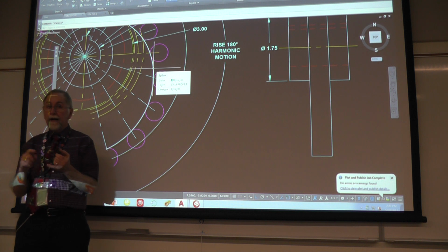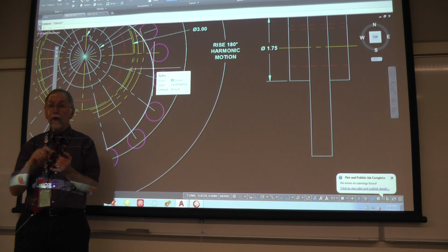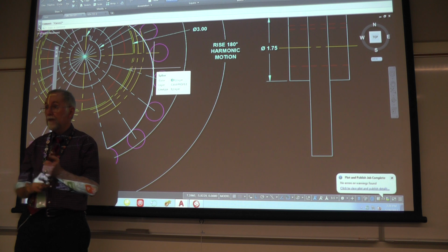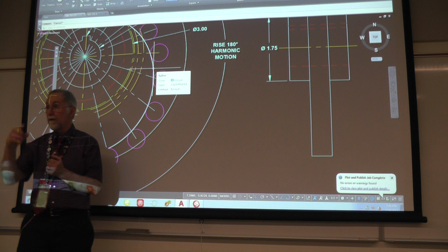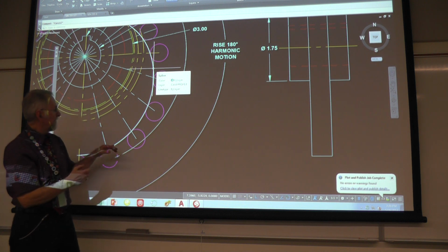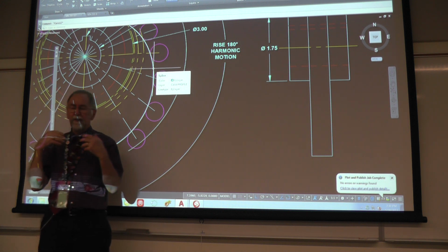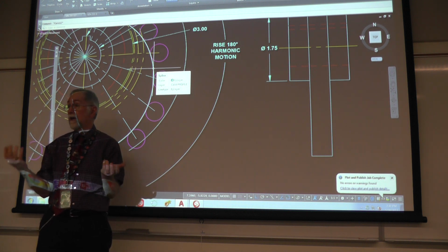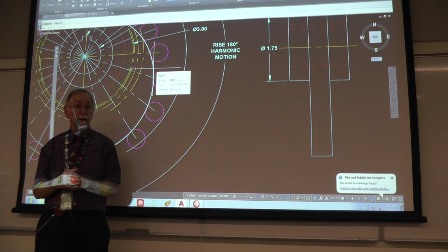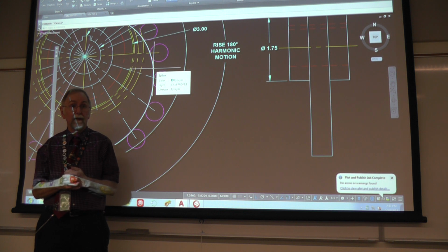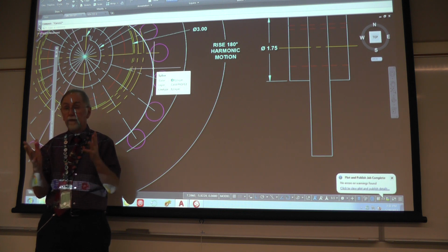If you're going to draw that, here's what I would suggest. Turn off all your object snaps except for the tangent. It'll look kind of funny to start off with, but eventually it's going to come around. A few of them will overlap the circle just a little bit. But again, we're just getting as close as we can with the tools that we have to work with, which is AutoCAD. Again, there's probably some better software program out there for doing a profile of a cam. I'm just betting, I don't know. So we're doing the best that we can.